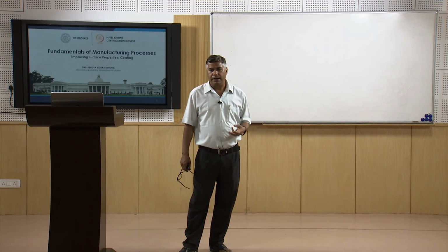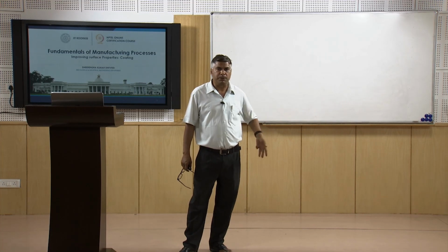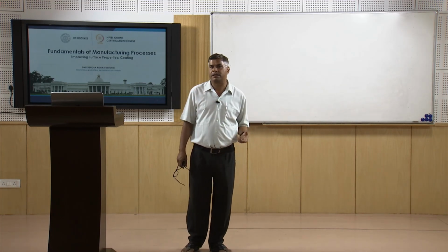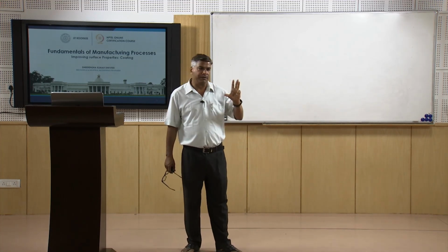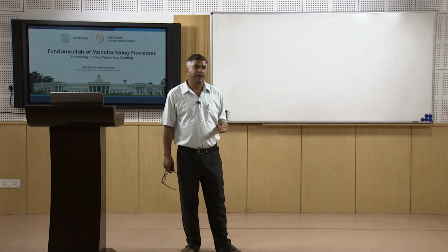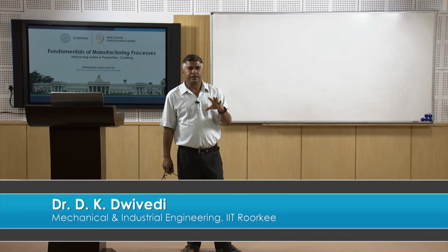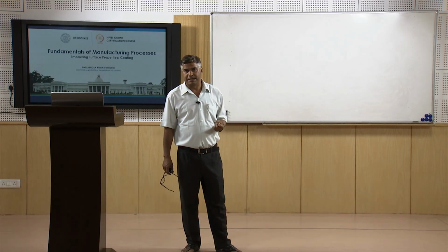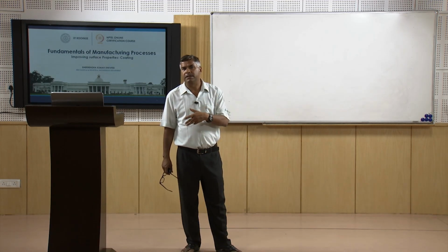These two parameters govern the quality of the thermal spray coatings. And in weld surfacing, there are various welding processes which can be used. Depending upon the heat input, control over the heat input, and the cleanliness of the weld is affected by the way the protection to the weld metal or the molten metal is given in each process.